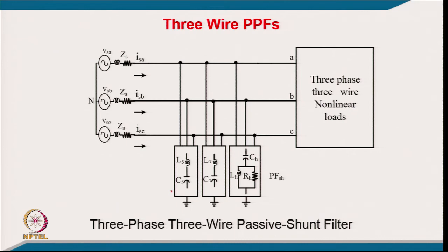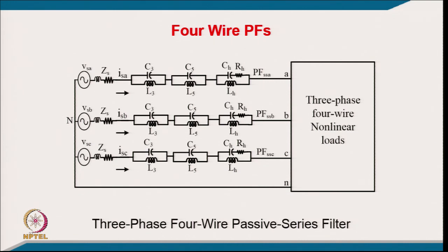So, that is the design criteria, because it is an engineering solution. You do not have an absolute solution here, you cannot completely eliminate, but certainly you can reduce the harmonics here. Well, this is typically your passive filter in a 3 phase 4 wire system. If you are able to block the harmonics in all 3 phases, they will not go through the neutral. Are you able to follow? Even with 3 single phase filters you are tuning for 3rd, 5th and then 7th and higher